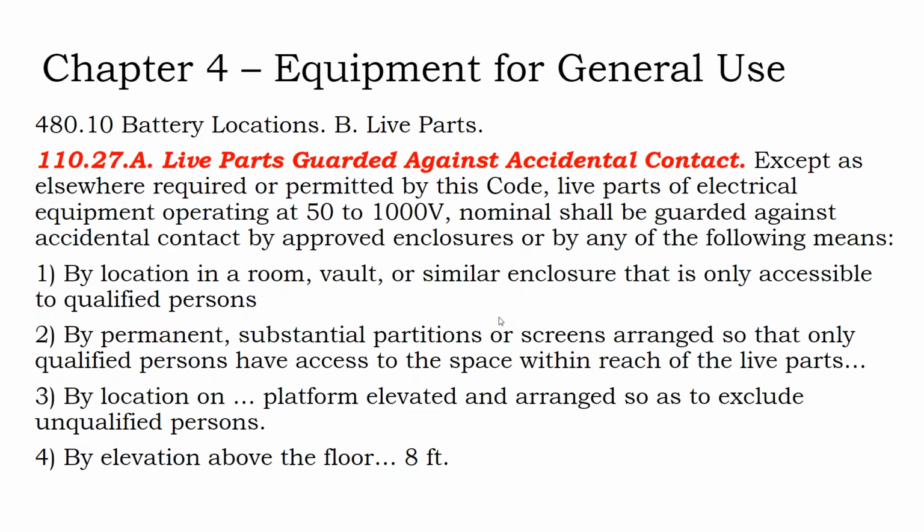So many installs, so that you don't have to have continuous ventilation in your whole room, in accordance with International Building Code, might enclose the batteries in a case and then ventilate the case continuously to the outside.